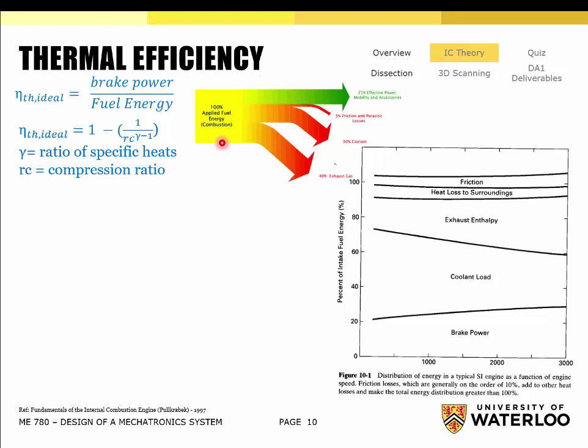I see a lot of people shaking their head no. So if you have 100% of the available chemical energy from the fuel, there are 3 main places that it goes. One of them is obvious: it's going to producing pressure inside the cylinder that's pushing down on the piston, that's producing work. But with that pressure comes excess heat. That heat is actually just getting blown out the exhaust, so you're actually heating up the air around you. If you contain a car within a garage for long enough, you'll heat up the garage quite a bit because all the exhaust gases are heating up the garage air. That is about 1/3 of the energy too.